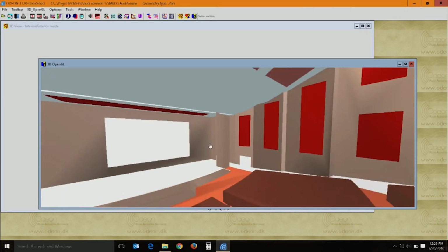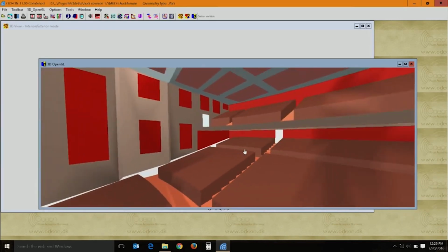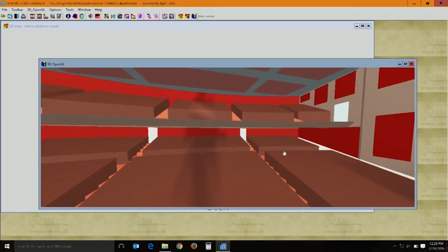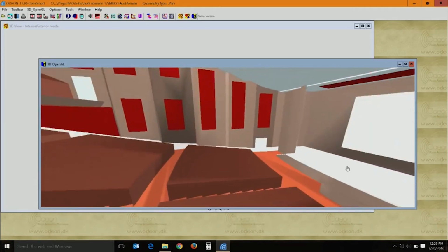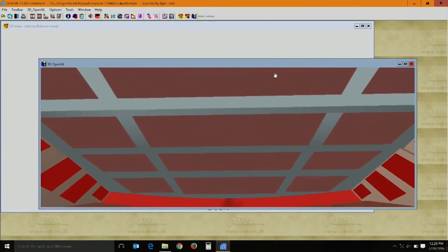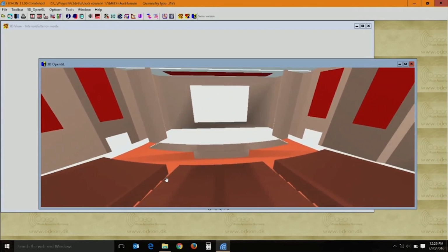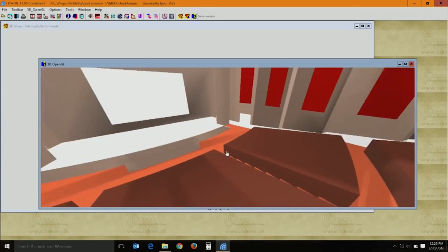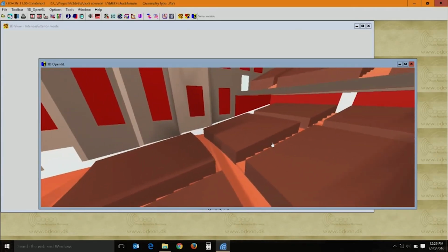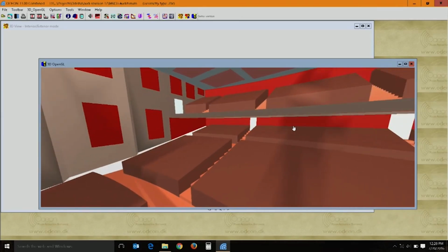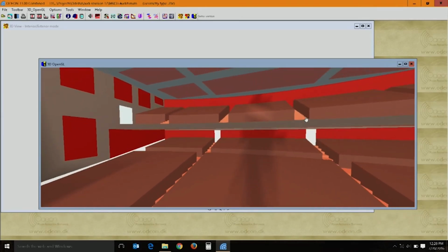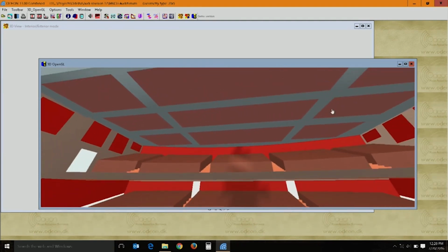A look and feel of it. You have the center stage, plus you have the balcony. This is a model which we developed in Odeon. So you have the ceiling, and I am showing you more or less an acoustically finished space. Each of these colors in this tool represents the amount of absorption they provide. The darker they are, the more absorption you get. For instance, there are certain lighter portions in the ceiling, they are gypsum panels, they are not much absorbing, a little bit of absorption, again frequency dependent.